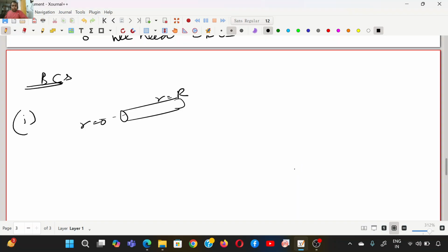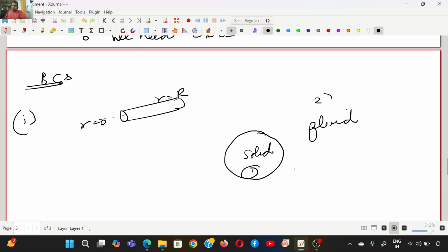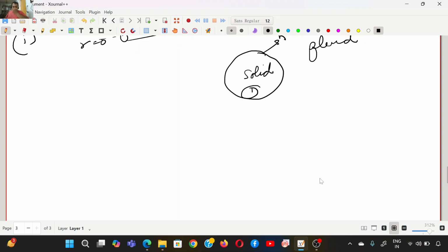Fine. So basically, this is medium one, the solid medium, the electric wire. The fluid around it is medium two. This is the normal vector pointing outward. So the heat that is conducted to the edge of the wire will be convected out. It will be carried away by the ambient. So that's a boundary condition that we can apply.